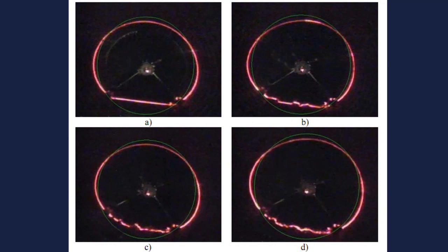And it looks like on all of these here, on these examples that we've got here, every one of them is seeing some level of deflection. And in fact, as you measure that, you would note that all 4 of those are outside of the acceptable 5% of deflection. So this is just an example of what laser profiling can do.